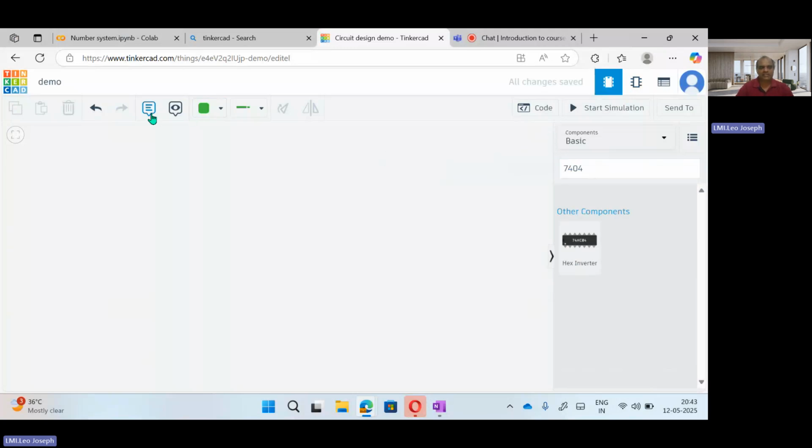So better I can write a note here so that you can follow. What are all the different ICs? 7400 is nothing but NAND gate. Okay. And then 7408 is nothing but my AND gate. Okay.